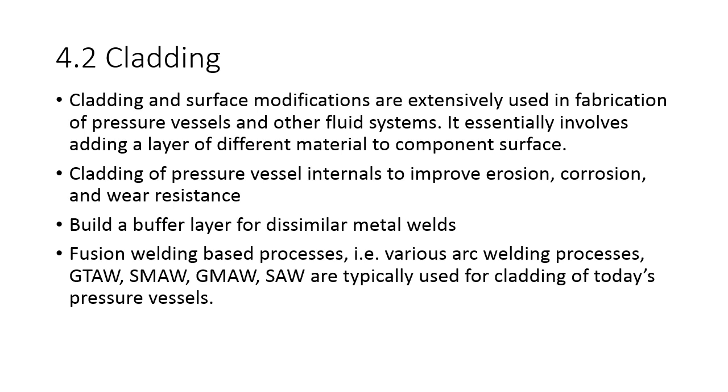So with pressure vessels and valves, pipes, there's a lot of times that you're going to need a certain corrosion resistance or material properties to keep a fluid from corroding or destroying your metal. So if you're going to make something out of a nickel alloy, it would be super, super expensive. So sometimes we'll clad it. We'll put a layer of, let's say, nickel or stainless steel on the inside of a boiler or pressure vessel or whatever. And then the outside will be carbon steel.